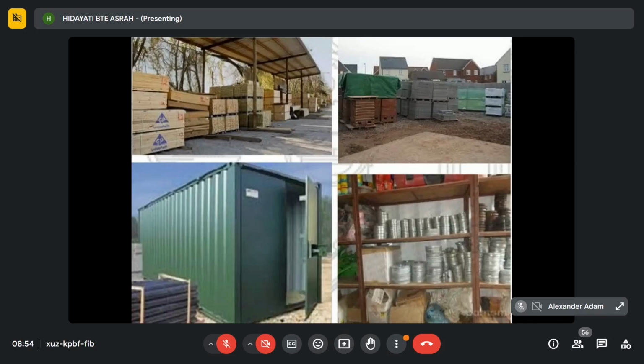Brick and blocks also need to be stacked in stable piles, and you cover them sufficiently. The brick or block cannot be directly in contact with the ground. You need to stack them in stable piles and cover them sufficiently, because you don't want the brick and block exposed to rain or high temperature, because it will affect the properties.